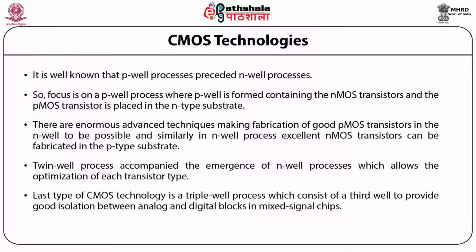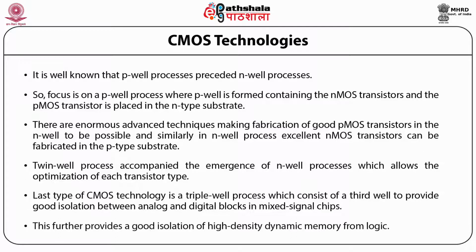The last type of CMOS technology is the triple-well process, consisting of a third well to provide good isolation between analog and digital blocks in mixed-signal chips. This further provides good isolation of high-density dynamic memory from logic.